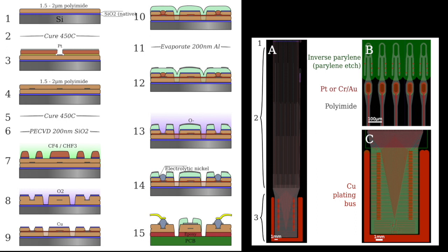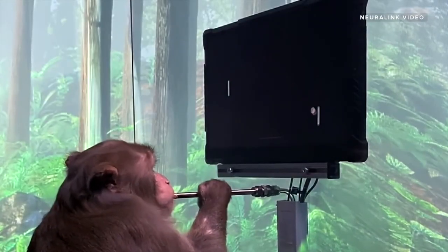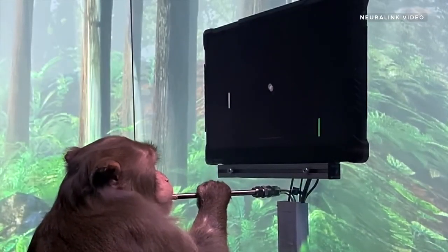Now, in the case of the Neuralink design, they do not use deposited nickel and have a second wire of gold that they connect to the platinum trace. Rather, they use flip chip bonding to make contact between the threads and the circuit board of the link. A tiny ball of soldered metal is deposited directly onto the circuit board for each point of thread contact.